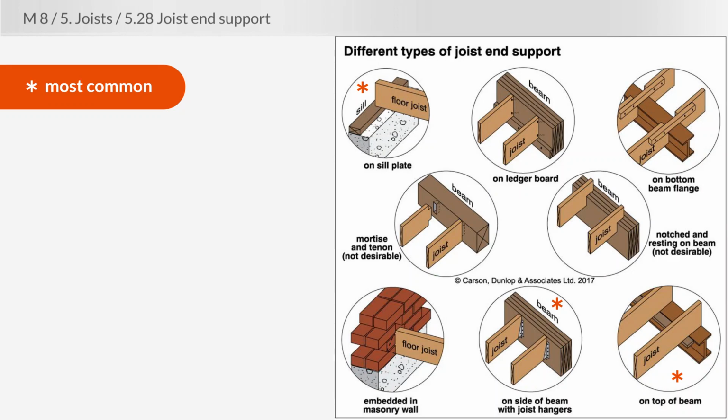At the lower left, where our floor joist is embedded in a masonry wall, we tend not to do that anymore because that has a tendency to cause rot to develop at the end of the joist.